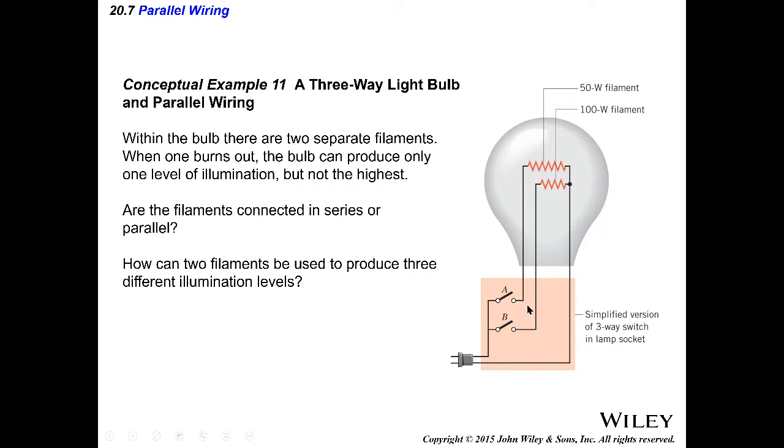When you have A and B together so that it's parallel, you can now ask, what is the new wattage? The fact that this is 50 watt, and now you assume this is a certain voltage. Maybe you call it 24 volts or you call it 110 volts. Try it out yourself. Let's say it's 110 volts. Then when they tell you it is 50 watts, that means that the resistance of this is, you have to work it out. It is V squared over R, and it is 50 watts. You can figure out what is the R, all right? And then you also can figure out what is the R here.